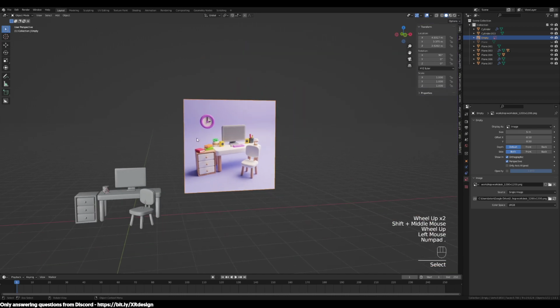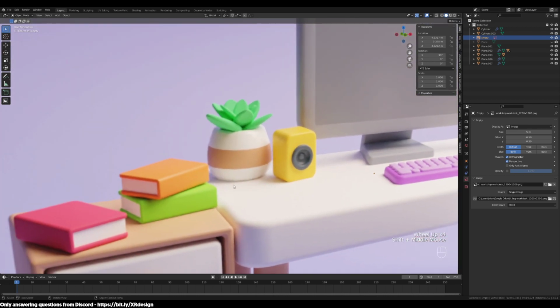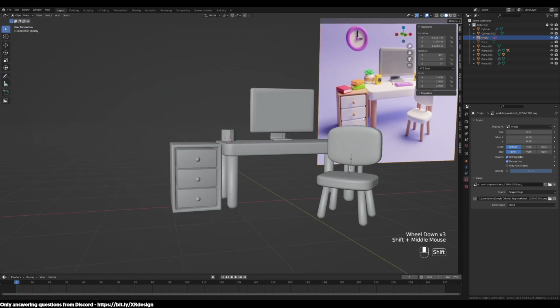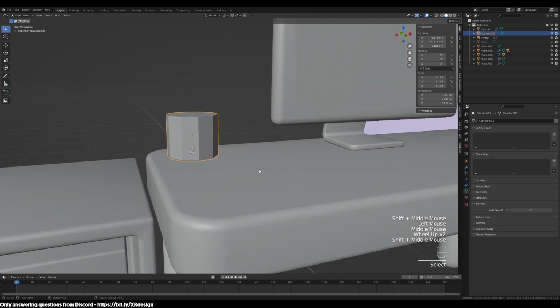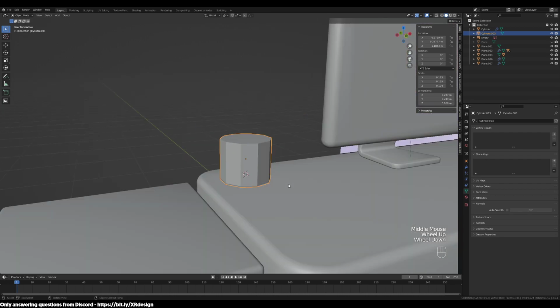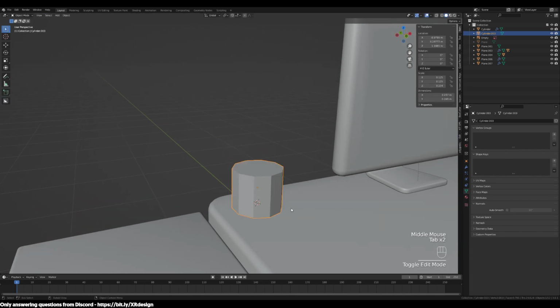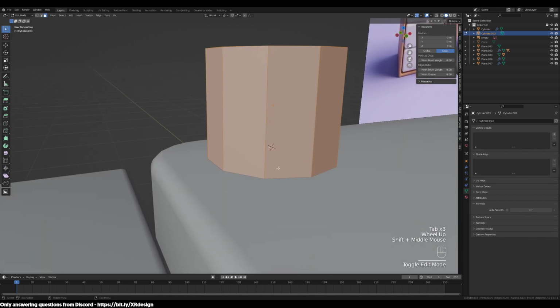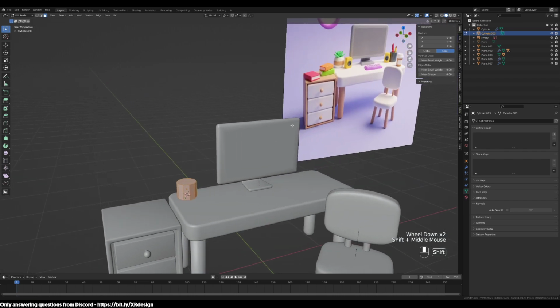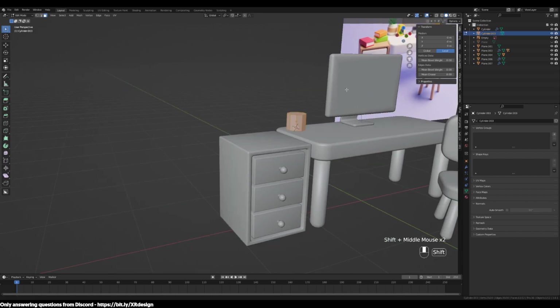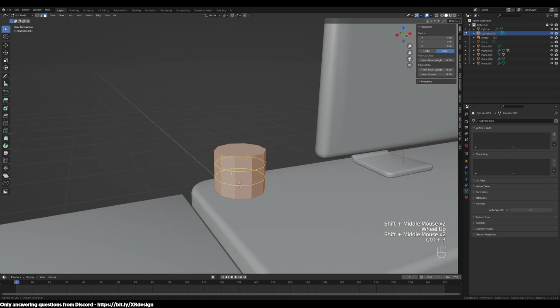If you go back to the image here, you'll notice that the base is a little bit smaller than the outer circle here. So we're going to achieve that by adding some loop cuts to the middle. Okay, so hit Tab, Control R, and let's add 2, maybe 3. Let me see. Okay, let's add 2 loop cuts, or let's add 4 actually. So 4 cuts,